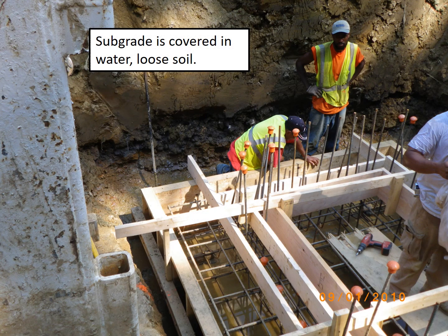Here's a case in a riser construction where I would just note that while the formwork and everything looks pretty good, and I won't comment on the fact that maybe these side slopes are a little bit vertical and unsafe, do look at the subgrade here. You can tell that it's just covered in water and loose mucky soil. So imagine when the concrete gets poured in there, it's just going to get all sorts of disturbed and intermixing with that water and produce a lesser quality material.